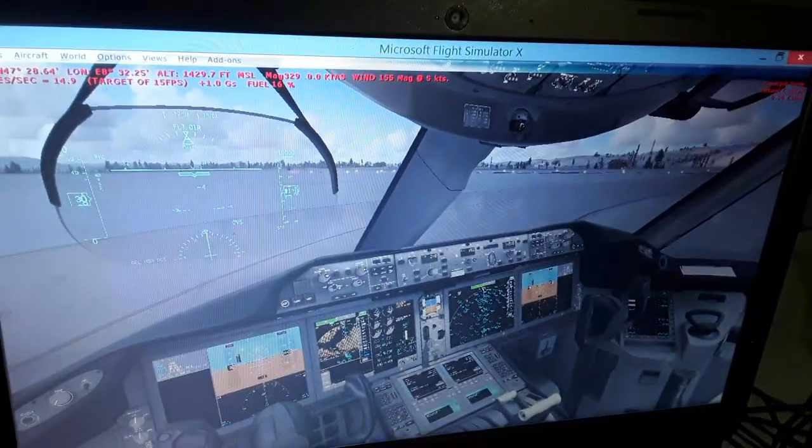We have also the navigation display, the horizontal and the vertical. We have other aircraft that fly around our own aircraft, displayed from the transponder, the ADS-B transmitter receiver, which transmits a radio frequency to other aircraft, and the air traffic control receives from other aircraft.